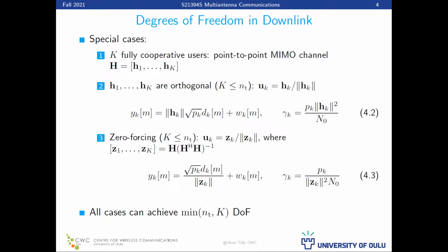And the receiver would be just U. Again, just take the SVD of the Hermitian matrix. Apply this as the precoder, U as the receiver, and get the diagonal. You get these 4 parameters. You can do both transmit and receive beamforming.